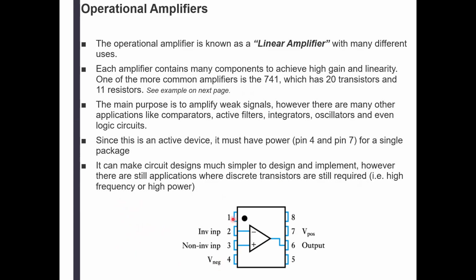There are some other pins that at this point we're not going to talk about, and this is basically to set that 0 point within that circuitry. It's called offset null. At some point we're going to have an opportunity to set that, but usually we won't need that. But I'll show you that because it's there, and I want you to know that this exists. And sometimes you do need to set that 0 point.